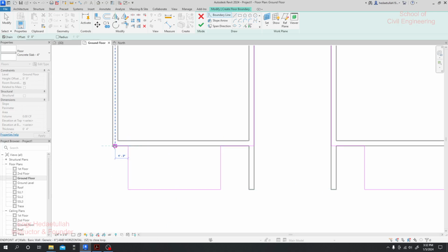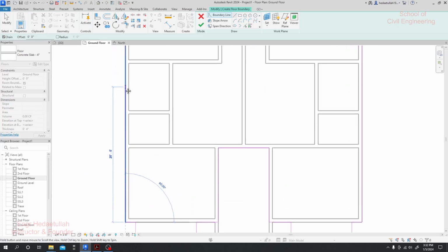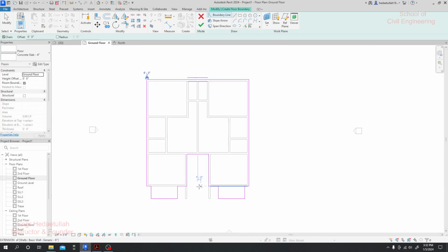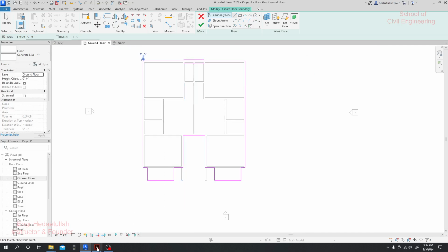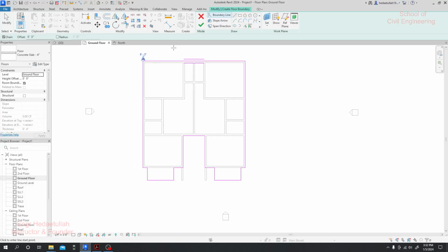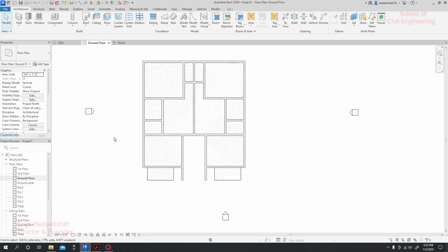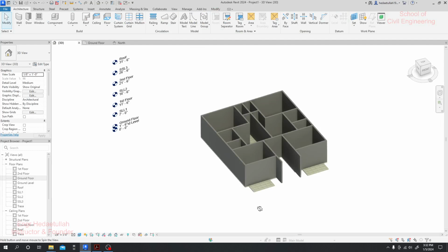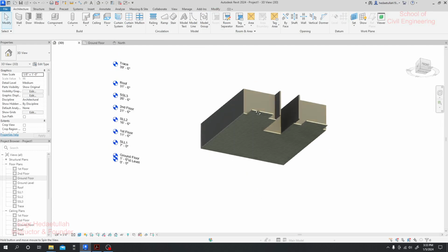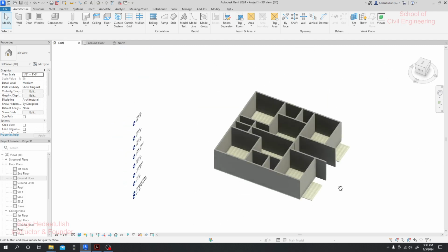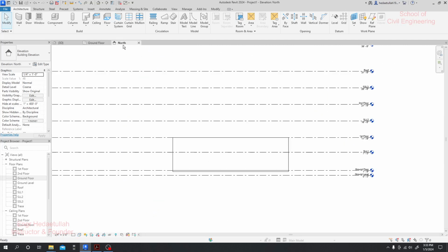So I'll take 9 feet, and we're able to manipulate that later, nothing to worry about it. You see, we have created all our boundary. I will again go here. So everything is okay. When everything is okay, just simply click here and see, it's done. And if we go here to 3D view, you can see a slab portion has been created at the bottom. Okay, it's done.